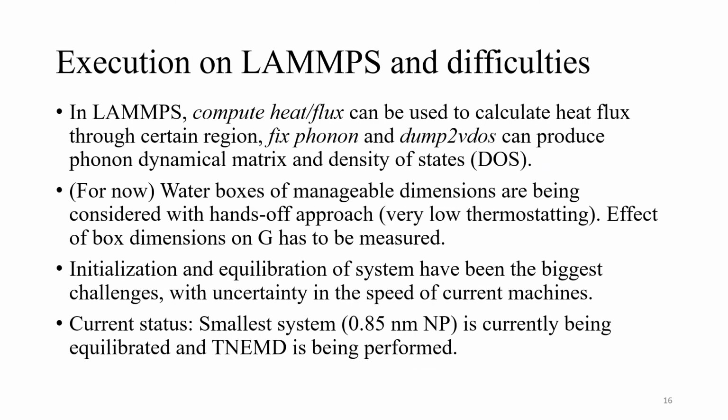So the problems that we have. First, I'll try to summarize what we can do in LAMMPS. LAMMPS provides computes, like the heat flux compute used to calculate heat flux, and fixes like fix phonon, where we can calculate phonon dispersion and the dynamical matrix, and dump for windows of vibrational density of states.